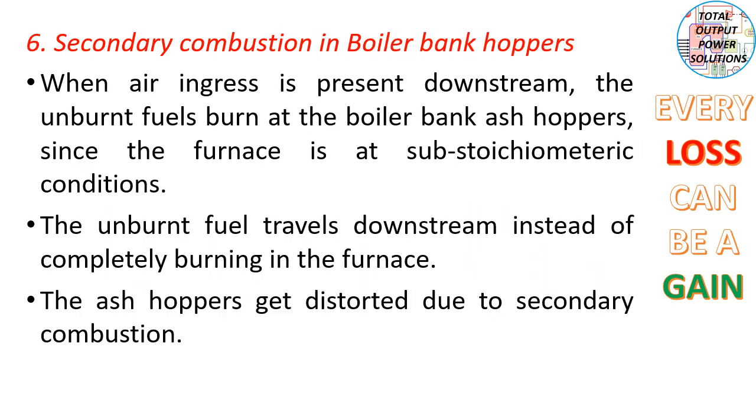Then secondary combustion in the boiler bank hoppers. When the air ingress is present downstream, the unburnt fuels burn at the boiler bank ash hoppers since the furnace is at substoichiometric conditions. The unburnt fuel travels downstream instead of completely burning in the furnace. The ash hoppers get distorted due to secondary combustion.